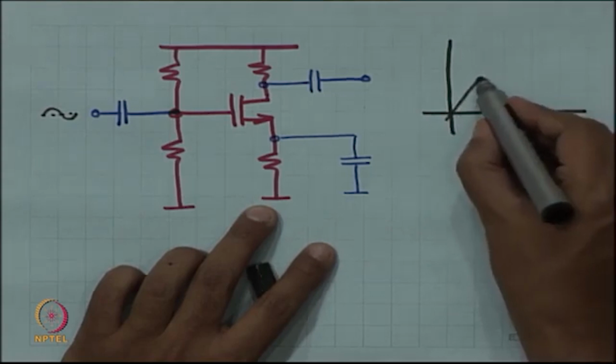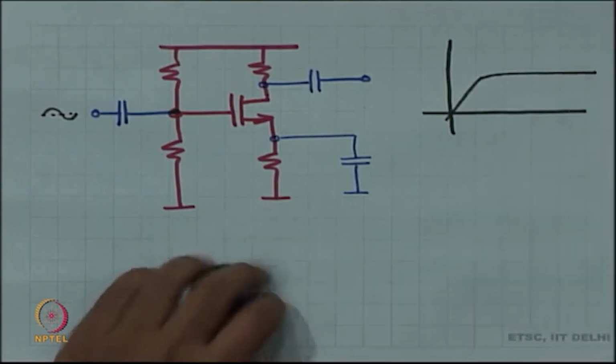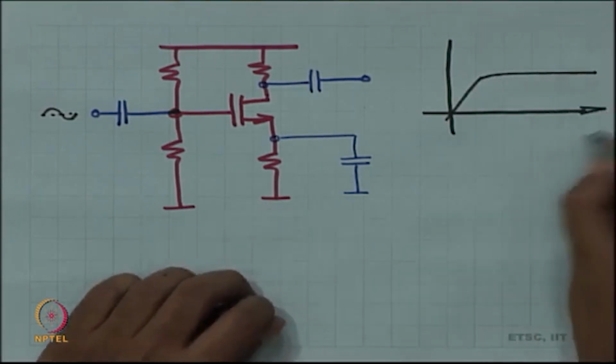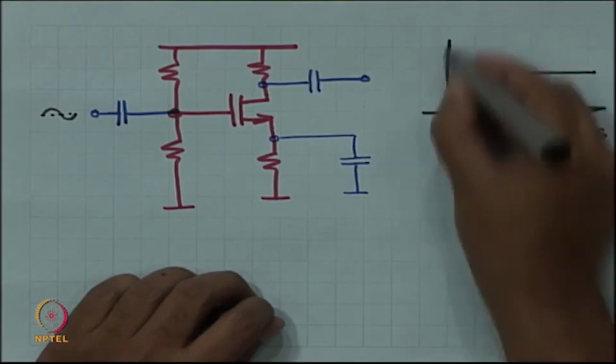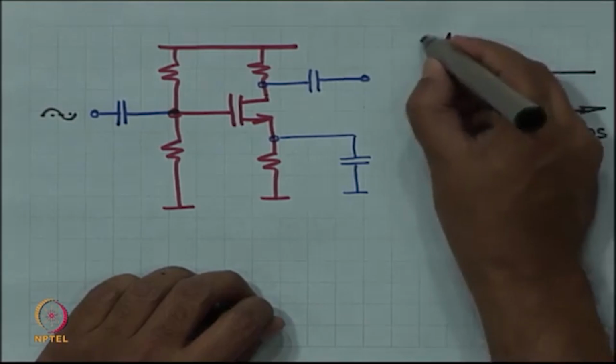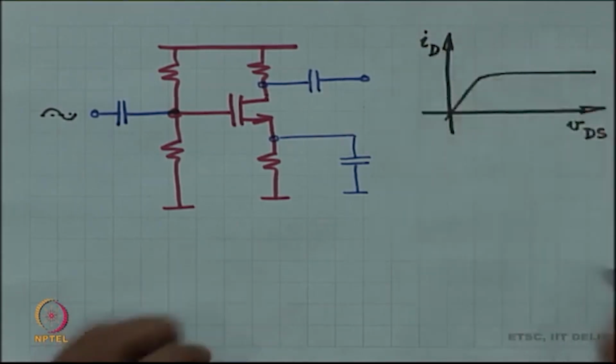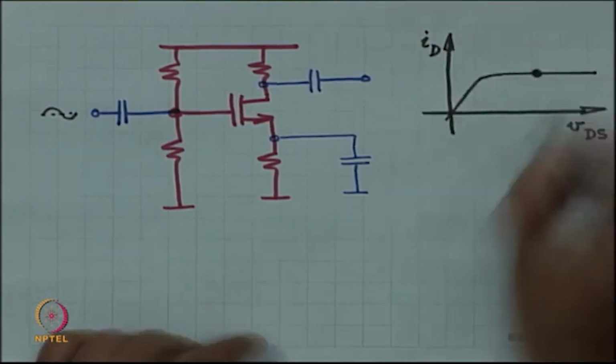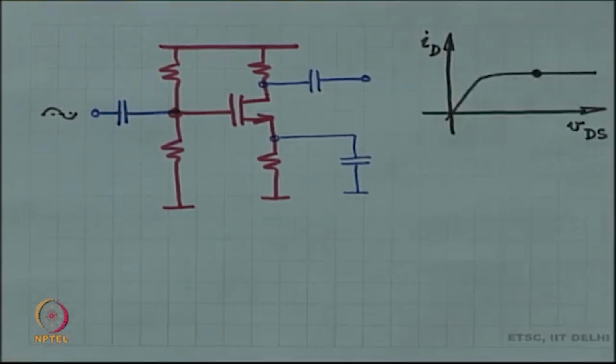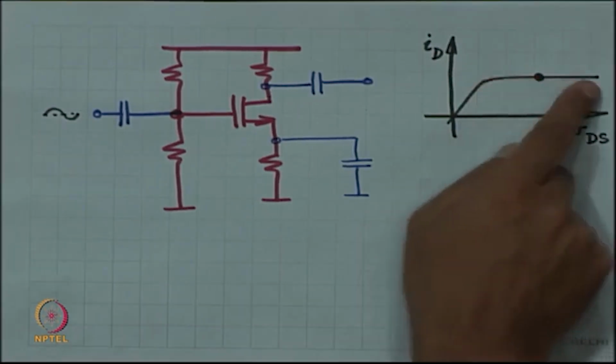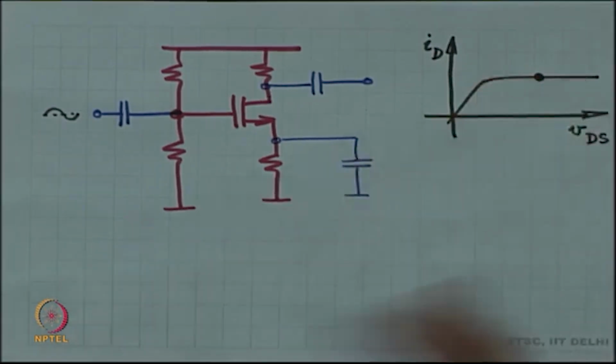Remember, you had set the MOSFET at an operating point, but you need to remain in the flat region of operation, otherwise the slope of this line is going to become low and therefore the gain is not going to be enough, and so on.